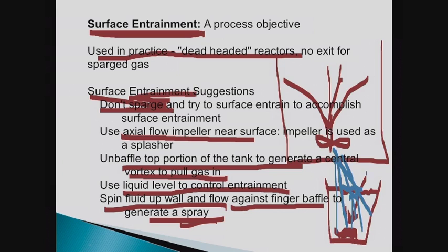Big difference. So since you're doing coffee anyway, you might as well go ahead and do that experiment. Use one straw, and next time use 5 straws and see what happens. Big difference. The one straw has a very small D over T ratio. This is 5 straws. First thing is the coffee doesn't know it's 5 straws. It just knows that it's a big diameter impeller. All right, you know it's 5 straws, but the process doesn't. Anyway, so 5 straws is a real great mixer as opposed to a single straw.